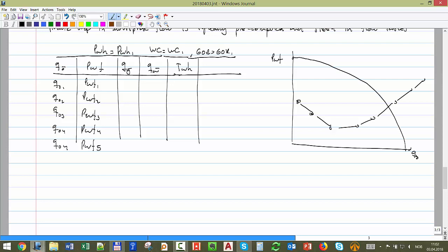So for example, if I have an IPR, to make the intersection, another trick that is also made is that I also convert the IPR into a series of points, that you will see next week when we talk about Prosper. And then to calculate the intersection, you don't have to be using a solver, you don't have to be using anything, you just make the intersection between two straight lines, which is very simple, one equation that you can write very easily.